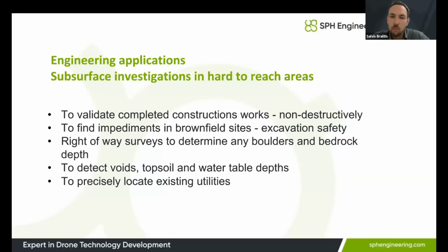And using our drone-based GPR, they were successfully flying these vertical tall walls and mapping out what were the actual block depths of those retaining walls, and everything came out that everything was built according to spec. The other alternative method would have been just physically drilling holes, and that's obviously an invasive method no one wants to do once the works have been completed.